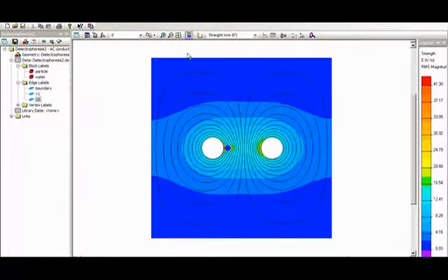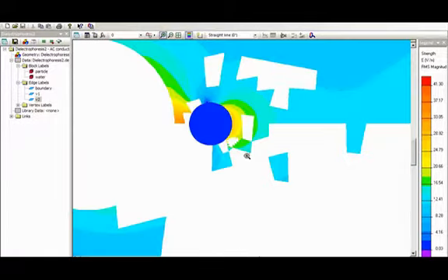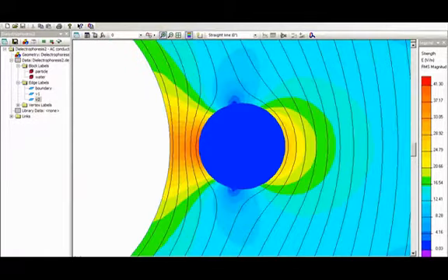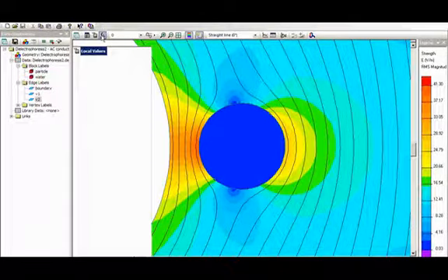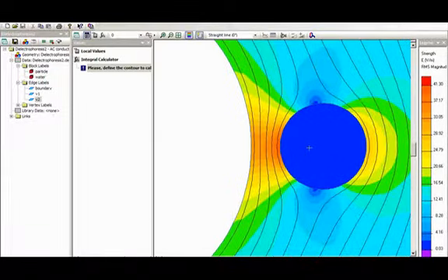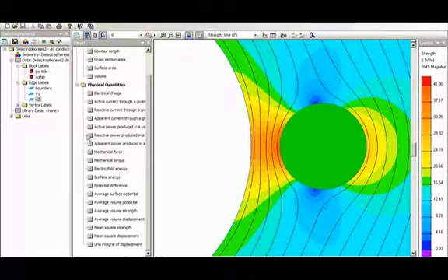Okay, this is the equipotential plots, and we'll get close to the dielectric particle here. This shows the relative field strength and the equipotential lines. And I'll go ahead and look at the force acting on the particle. I'll make a contour around. I need to go to my tool here, and once again look at mechanical force.